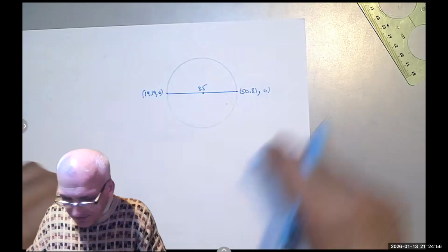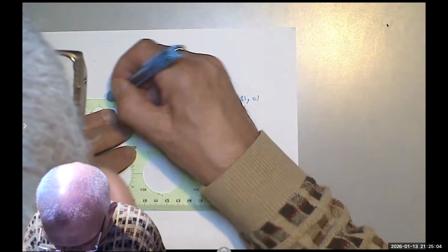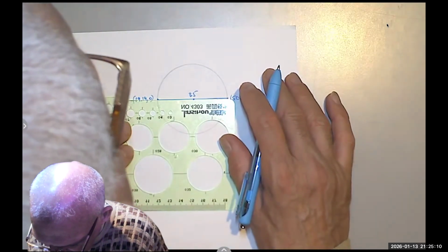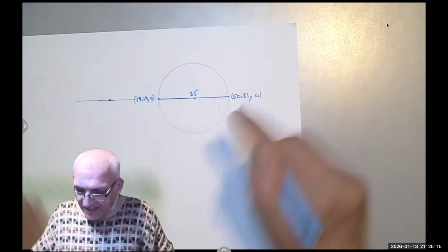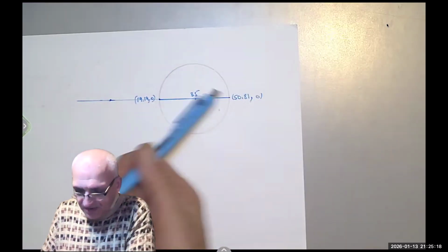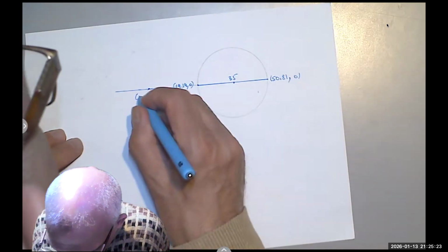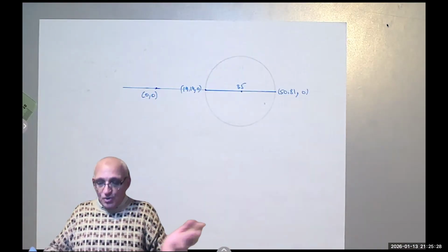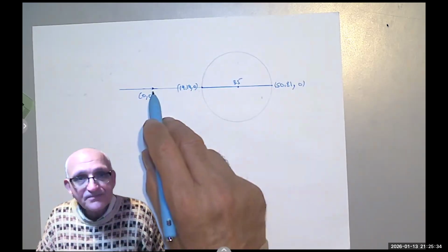So the 0 is somewhere here. And since we had sigma x and sigma y, we got sigma 1 and sigma 2 belonging to that plane, but sigma 3 is the origin because Z didn't have any stresses, so the stress on it was 0. The normal stress, or the principal stress, was 0.